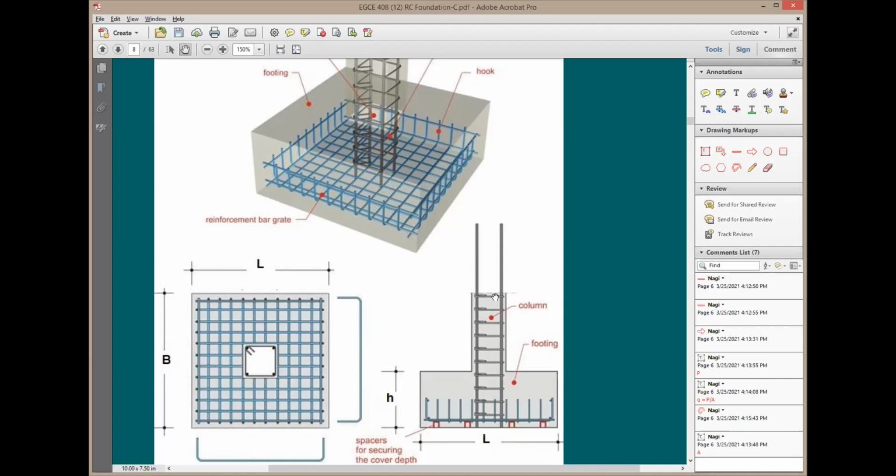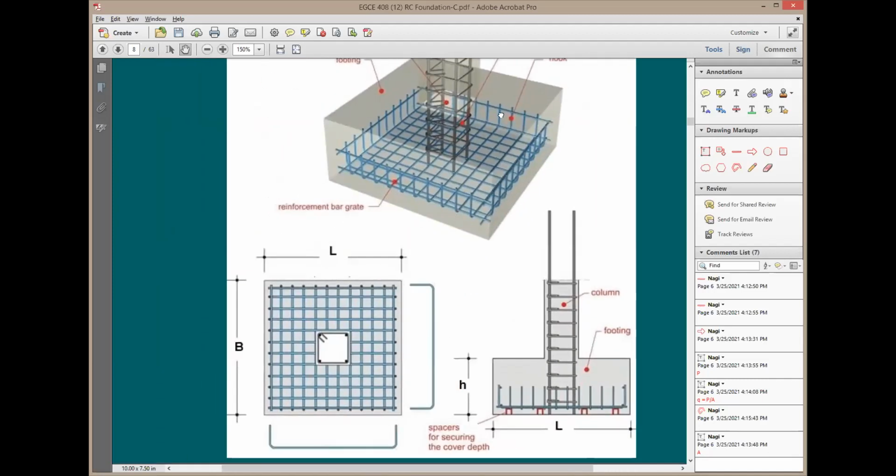Now, when you look here at the column rebars, in this elevation, here are the column rebars, some ties and stirrups, and here's the footing. Now the question is, why do I have the reinforcing bars at the bottom and not on the top? In this concrete pad, it's not really a simple support. Does it mean tension is going to be at the bottom and not on the top? Most likely. Okay, so yes. Tension usually in a case like this is going to be at the bottom.